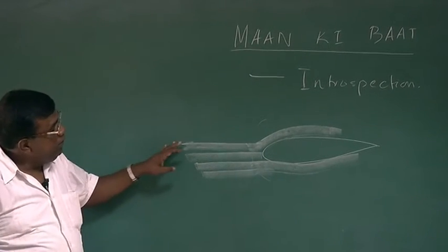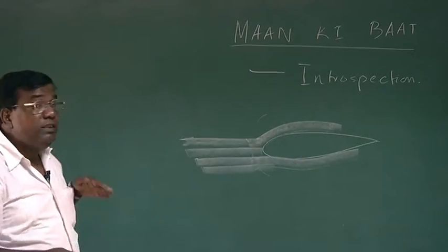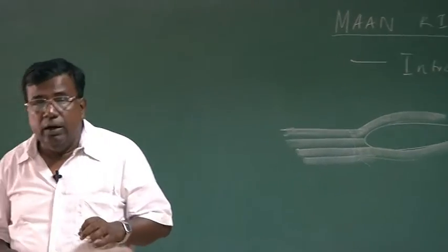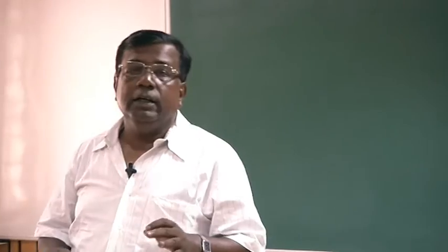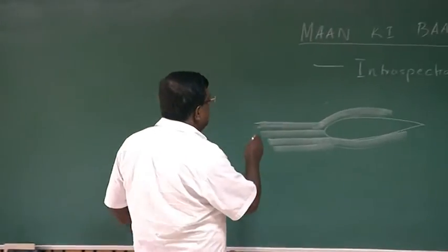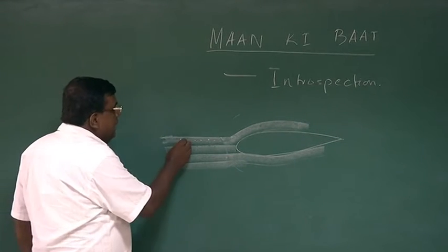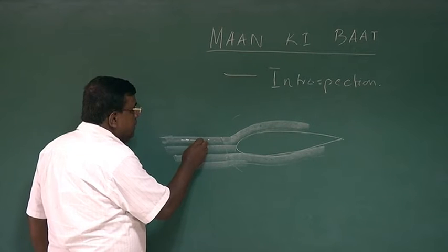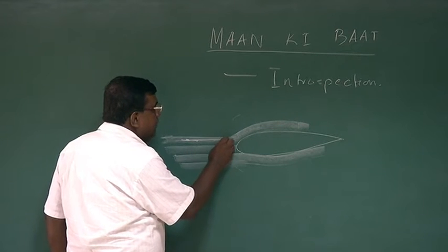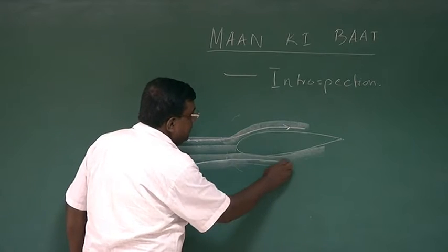First, if I want to represent this flow, which direction the flow is going, one of the ways is to define streamline. What is a streamline? You imagine those points in this flow, and if I draw a tangent at this point, that should give me the direction of the flow. So this becomes your streamline. This is another streamline, okay?